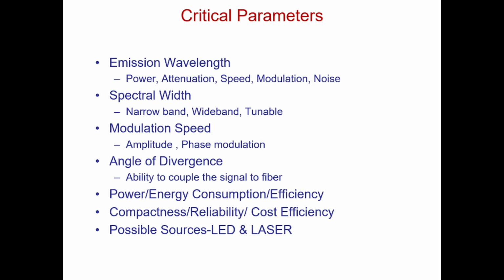But a tunable source means that if there are multiple carrier frequencies like FC1, FC2, FC3, then we have to design our parameters in such a way that they can accommodate all these spectral frequencies. So the spectral width is very important in considering the optical sources. We have either narrow band, wide band or multiple carrier frequency inclusion, which is basically the tunable.